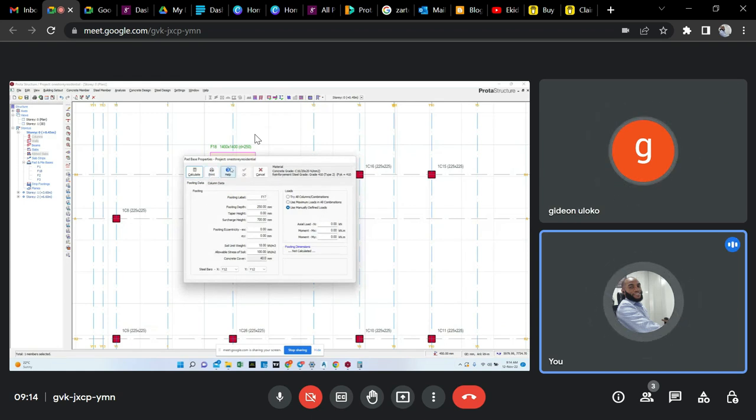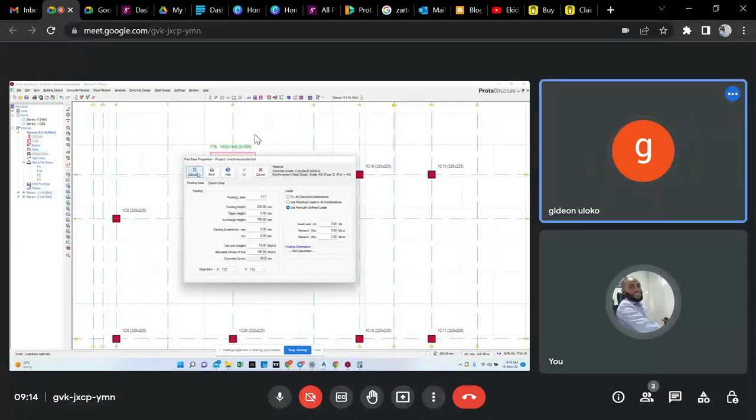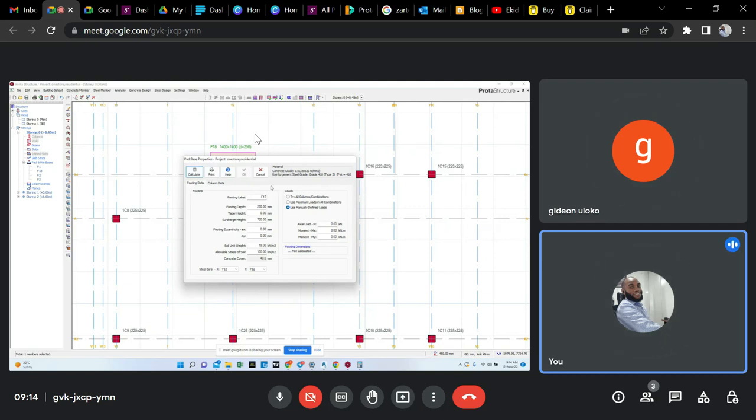Now, hold on. You will see an error if you click on calculate because you did manual define load and your actual load is still giving you a 0. So once you make that kind of change where you have to remove your moment, click back on the first option, try all combination. Now click on calculate, else you have an error issue.